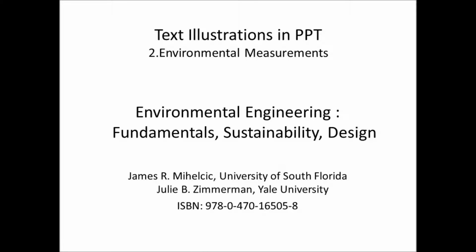Parts per million by mass, referred to as ppm or ppm sub m to designate the mass, is defined as the number of units of mass of chemical per million units of total mass. Thus, we can express the previous example mathematically, where ppm sub m equals g of i in 10 to the 6 g total. That's equation 2.1.